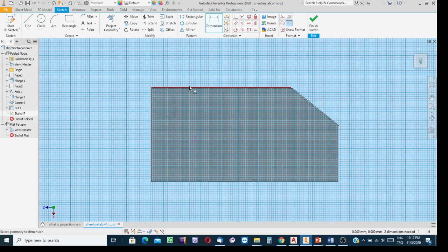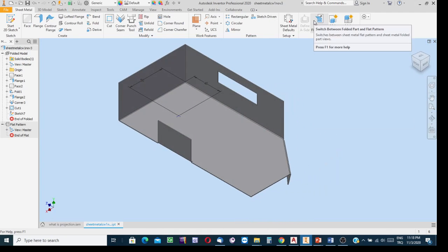Dimensional constraint from this projected boundary to the point, distance say that is equal to 50, and from this projection boundary to the point, distance let's say is okay, then 40, and then finish the sketching stage. You see over the surface I have such a mark. It is to be marked as the centroid of the surface of the emboss, and then the rest.